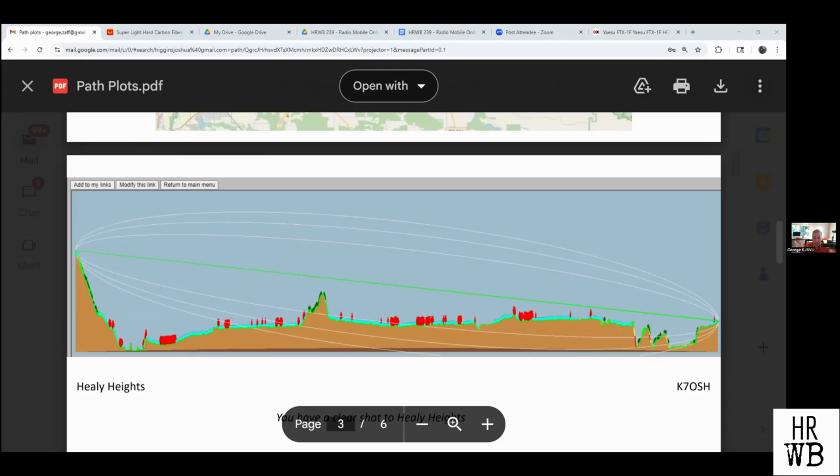A bunch of my friends are microwave operators, and one of them said something one time that I was really surprised by. I said, well, when you're doing a long microwave shot, do you do it from mountain to mountain? And they're like, well, we do in the contest, but in the commercial world, a more predictable path is mountain to ground and ground to mountain, as opposed to mountain to mountain, because that way you're cutting across the thermal variation. I never understood why that would be a thing. I would think mountain to mountain would be better, but he's like, no. You want to go to the ground and then back up to the next mountain. Okay, so